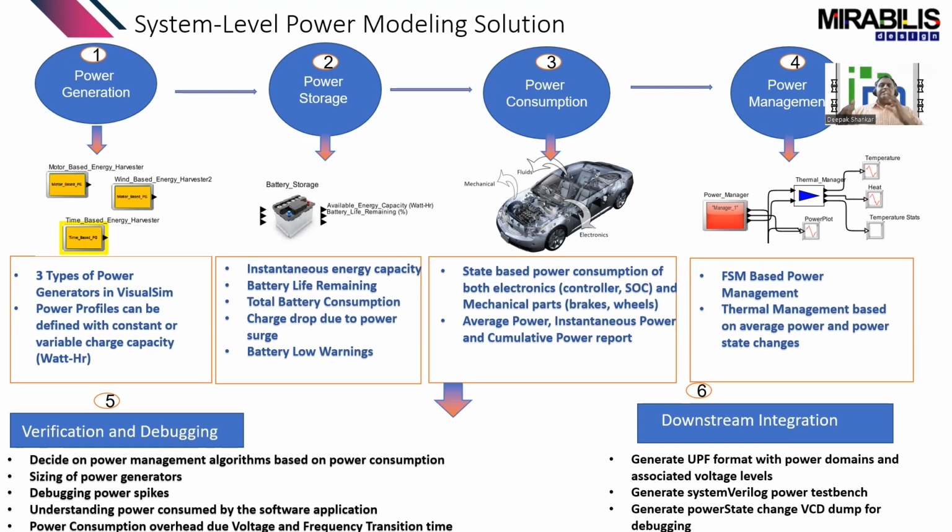so any of those. And that leads to understanding the thermal aspect, which is temperature and heat effects, both localized within an IP block, but also within the whole semiconductor or within the full system. Now, debugging the power spikes, things like that, definitely is very valuable. So you can reduce the amount of capacitance by potentially just using a scheduling algorithm to shift some of the software applications.